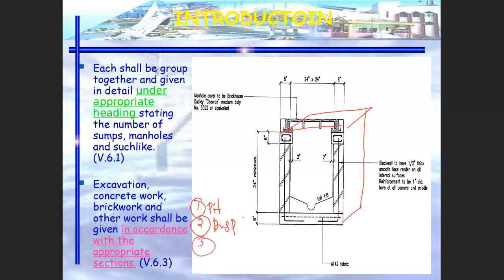Number 3, you have to look at what is below that. They say this is concrete bed. So under section F, you have to measure concrete bed. Once you have the concrete that is in situ, you should know that you have to measure formwork. So that is item number 4. Item number 5, you have to measure for reinforcement, or in this case, is given as fabric. So we take this one that we have to measure. Logically,